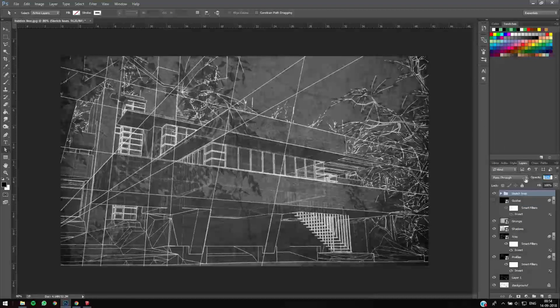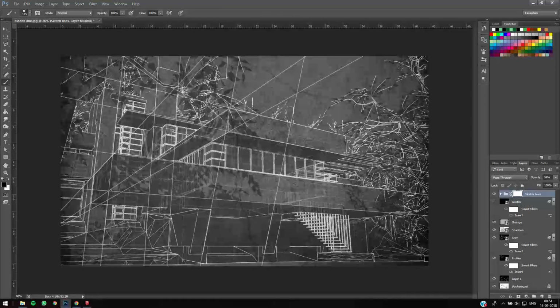of this line and put a layer mask on it. So this button over here puts a layer mask on it. When you put a layer mask on any object or group, you can use the brush tool to delete it, or even bring it back.